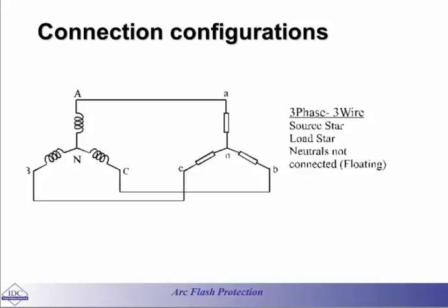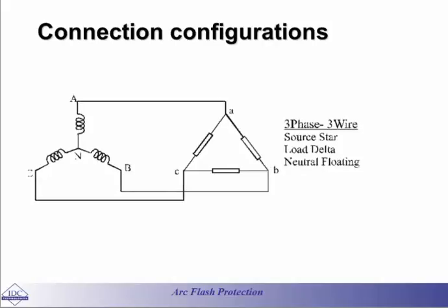Okay, that's your responsibility. You have to establish your own local ground and connect your neutral to that local ground. If the customer says, no, I'm not going to do that, in that case, the neutral point of them will be floating. And that may not be good in terms of some of the faults that may happen in the system, and they may not be detected at all.